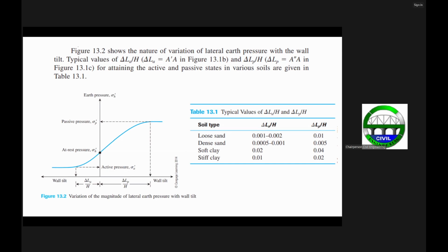If you have a smaller movement, then you can design the wall cheaper or at less cost. And also, granular materials can have better drainage, for example, if water will seep through it. It's always best to have good drainage because we don't want pore water pressure to build up within the wall. That can cause wall failure.